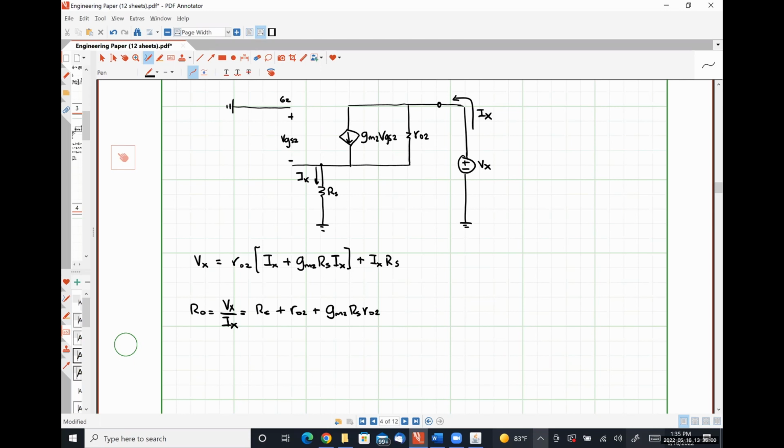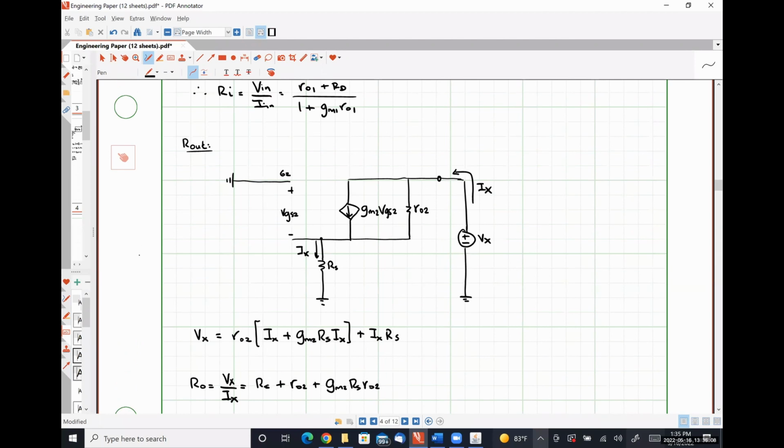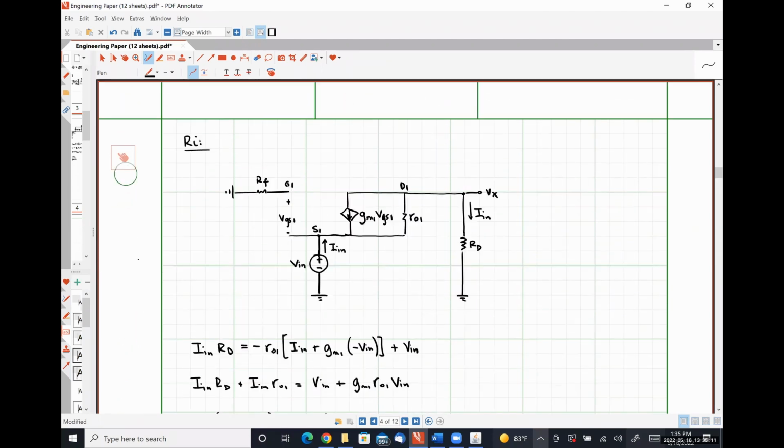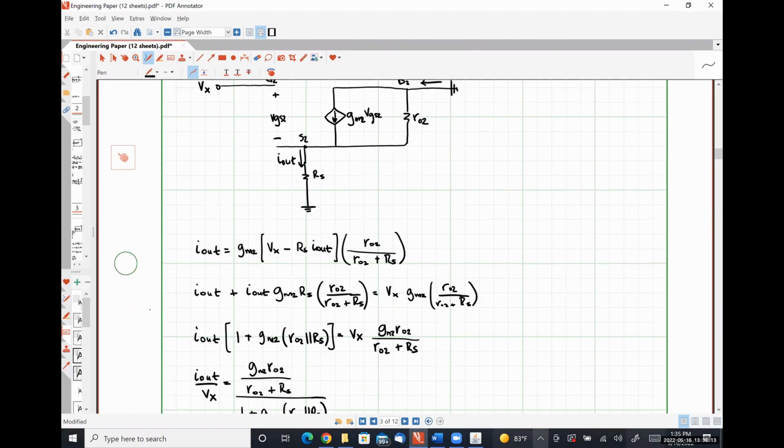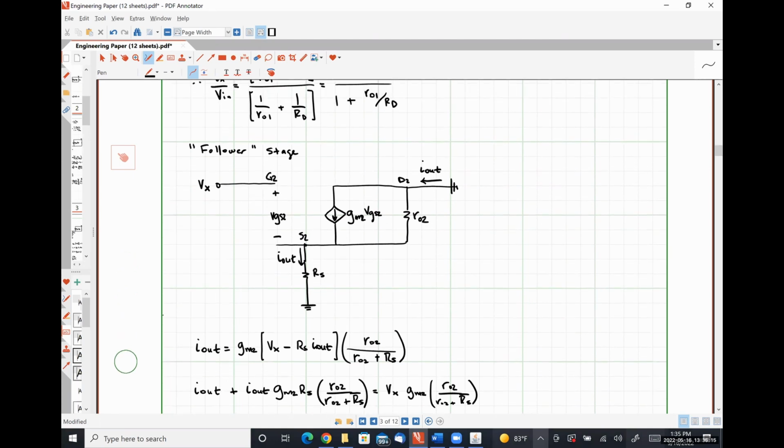And whenever you were going over the right-hand side circuit, why were you considering that a source follower instead of a common emitter or common, what is it? Source. So I technically wasn't considering it a source follower, because for a source follower amplifier, we would have been taking the output voltage at our source terminal.